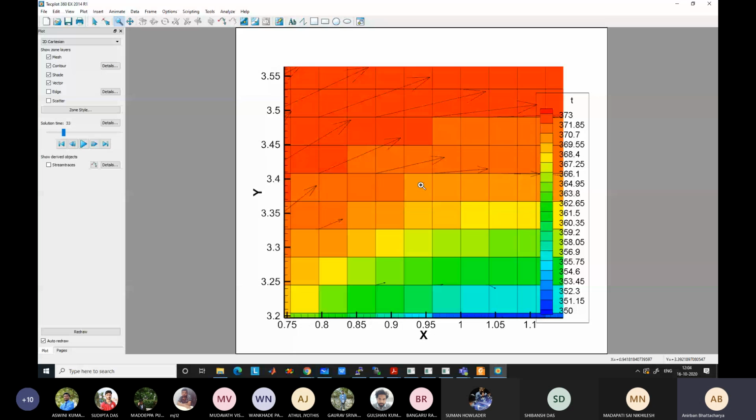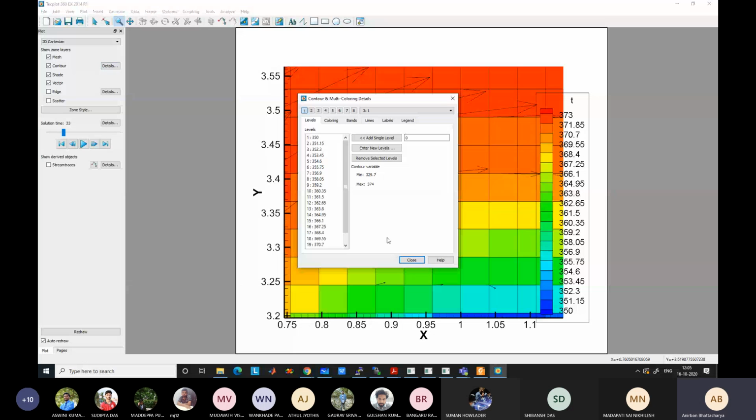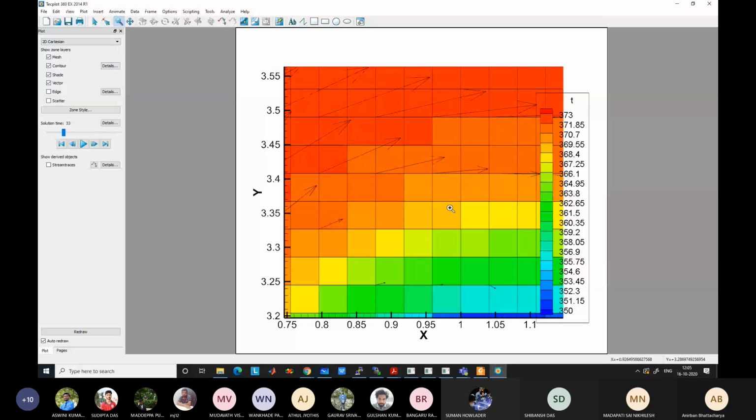So it is at the center, but you cannot say what the temperature value will be at, say, 80% distance, or say 10% distance from the boundary, because you do not have a separate value there. No solution is there. Either you can say that this is equal to the center temperature 370, or you have to do some linear interpolation to find the temperature based on the neighboring values. So when plotting, we do linear interpolation. Instead of this pixel view, you get nice smoother plots like this.